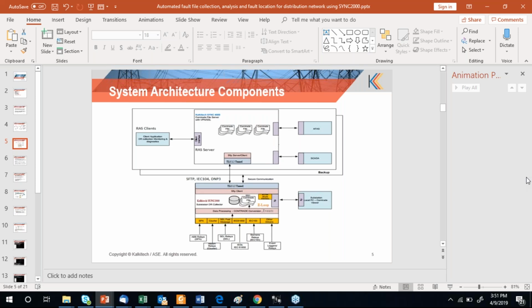For 61850, we have an automatic mechanism for events. Since it is a tag oriented protocol, from the tag itself we can analyze that this is the event. We can put the tag and the event details in 61850. So we can readily retrieve the events from 61850. Using the report control block or any other means, we can retrieve the events directly, automatically convert them into a suitable format, and then push that to the central system.